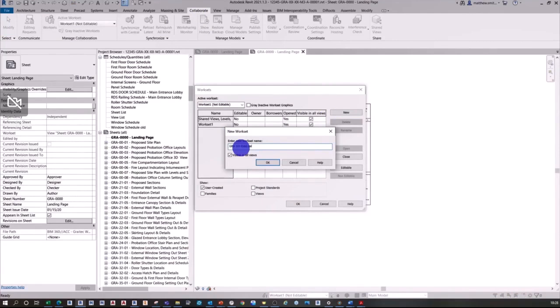We want to create a work set so that we can put the elements under those work sets, because then it can help us with the management of that. If we didn't adopt work sets, then there would be delays and some slight problems around people wanting to work on elements and them not being able to because somebody has already taken ownership. So we create the work sets almost as like a layer.